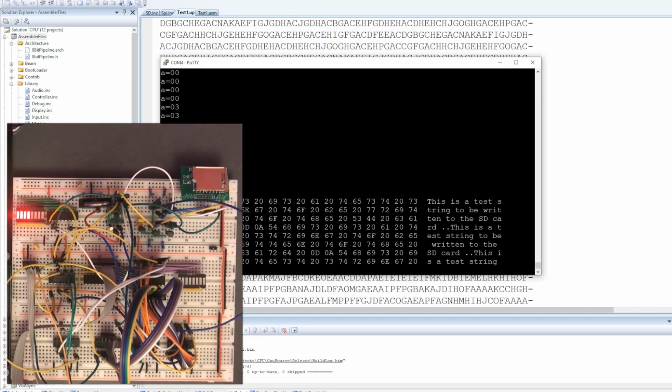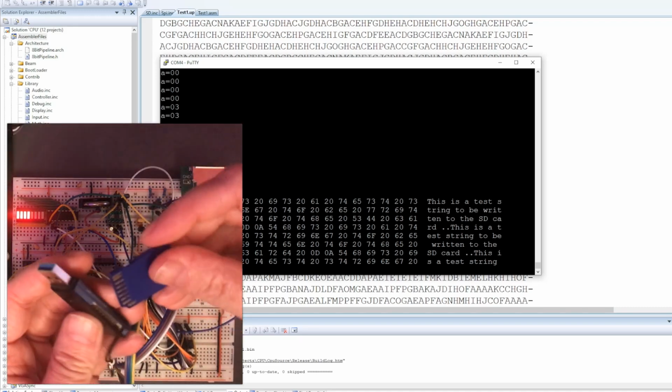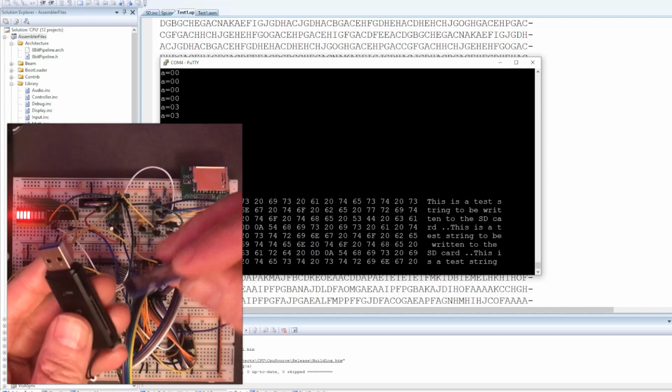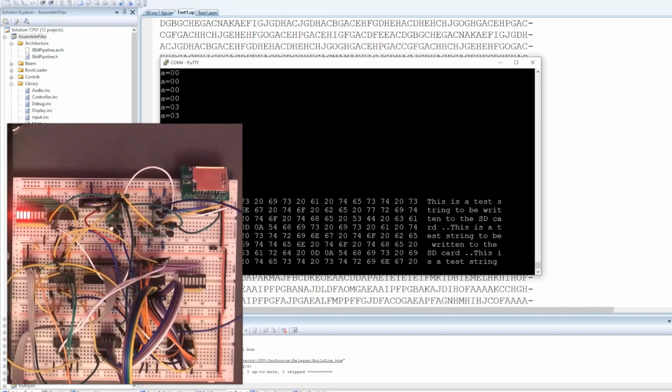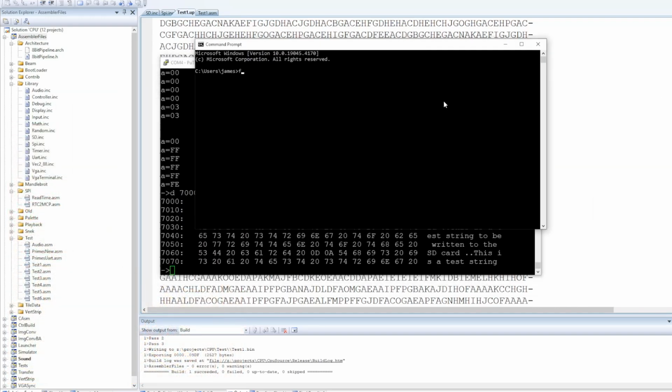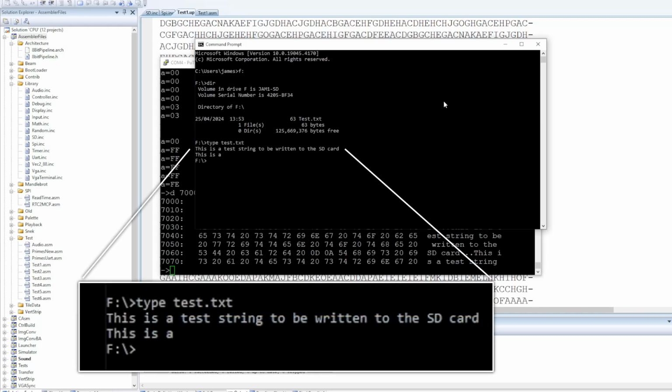As our final check, I'm going to put this SD card into a reader. So that is the text file I created. Awesome. The one thing to note there is we're not seeing the multiple replications of that string that we actually wrote, and that's because the file was only a few bytes long for the original message we saw, and I've not done anything at the file system level to tell it that there's more data there.